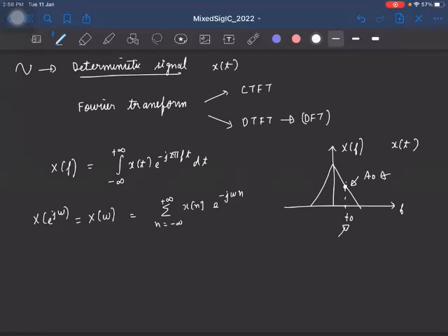What this really means is that around f naught, we have a band of frequencies. In a bandwidth of say 1 Hertz, the combined strength of this continuum of sinusoids is a naught. So what is the strength at any given sinusoidal frequency? That is a naught divided by the total number of frequencies, which is infinite, so it's essentially 0. This is similar to a probability distribution function, where the probability at any given point is 0.